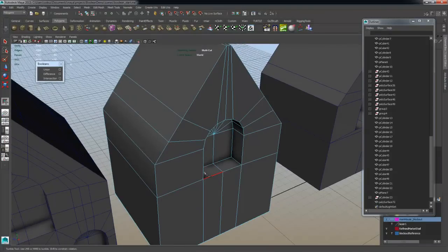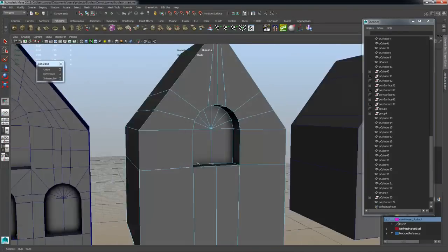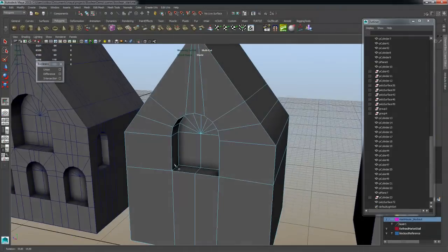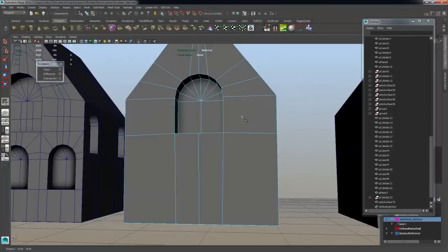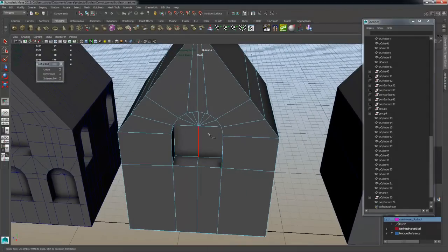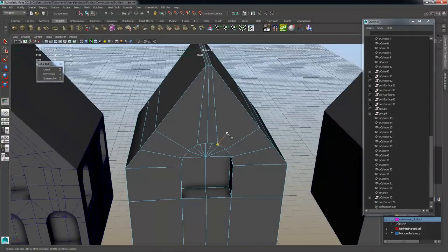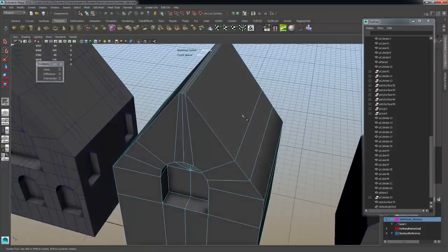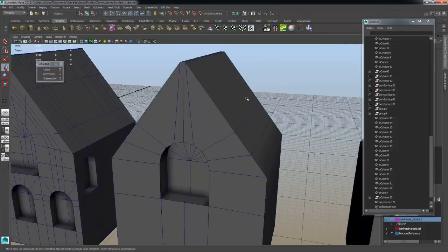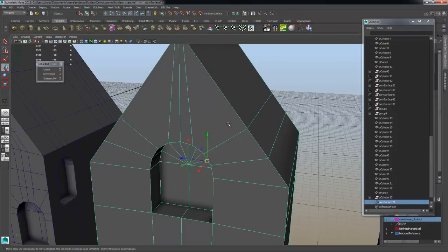Now, it does not mean that this operation works 100% every time. Like I said, if you have any weird geometry on your original mesh, then you will have some issues when trying to subtract, rather, not align. And what's going to happen then is either both of the two models will physically disappear, and that simply means that one of the two is incorrect, and you need to go and clean the mesh up.